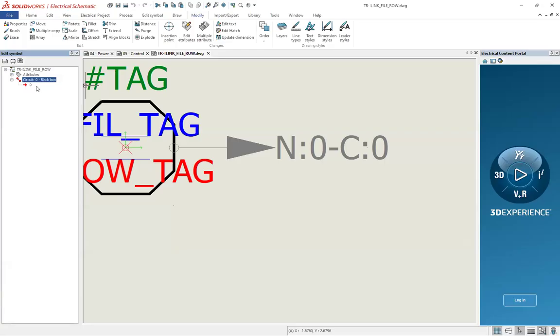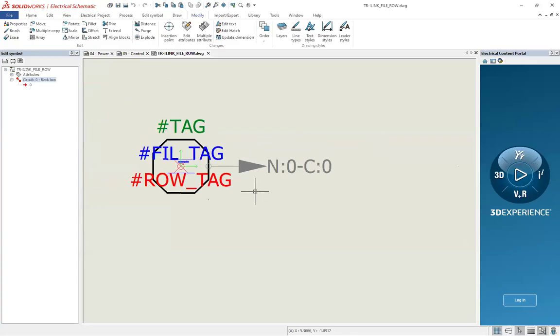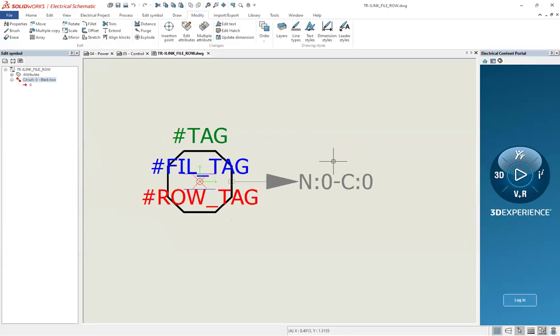At this point, I'm looking at time and how long this video has been dragging on, because again, this is a massive diversion from where I wanted to be right now, but it's all good. All symbols have circuits. Well, I shouldn't say all. Symbols that are going to connect to wires need a circuit because you need a place to land the wire, and SolidWorks will only allow you to connect wires to circuits. So your symbols will have circuits.